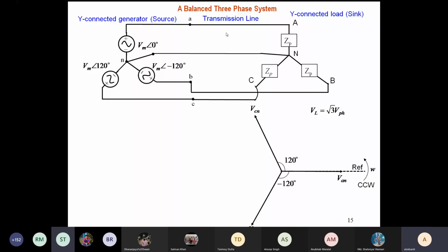Sir, the currents vectorially add up to 0 and also the voltages. So in the neutral wire, there will be no current anyway. So we will show it mathematically. I am not telling just a story. It will come out. We just found out now VA plus VB plus VC equal to 0. So we'll also find out what is the neutral current. So let us first allow the current to flow.